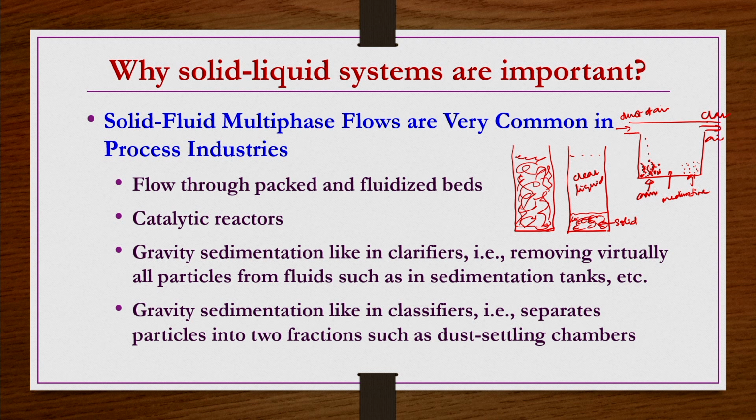So sedimentation tanks are like clarifiers, which separate virtually all particles from the fluid. Classifiers are equipment which separate the particles into different size fractions, like dust settling chambers, as discussed here.